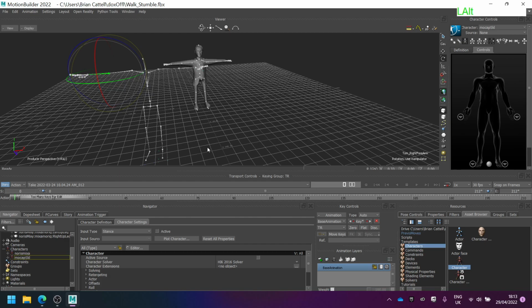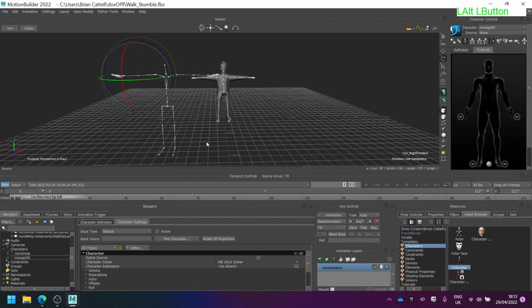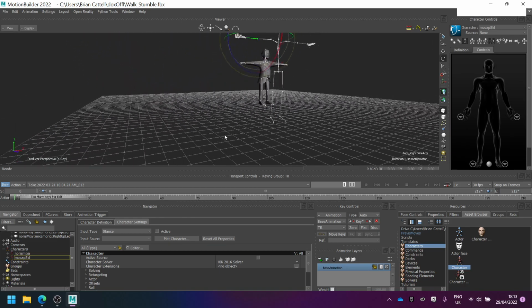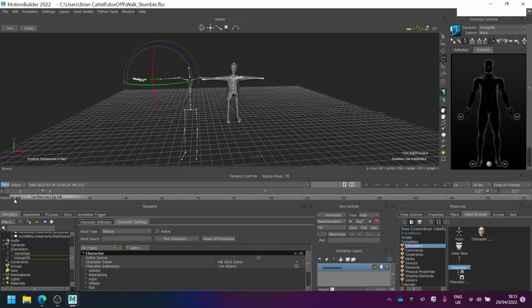Not that there aren't some things that you can do quite quickly again to redo them, but it can take a lot of fiddling, especially if your Mocap skeleton deviates from human norms too much, or if you've got a bespoke hand-created skeleton which has the right joint relationships but really unusual relative proportions. Okay, now the characterization process is complete.